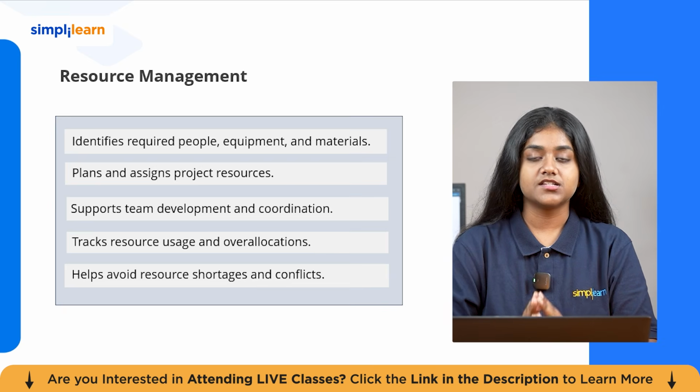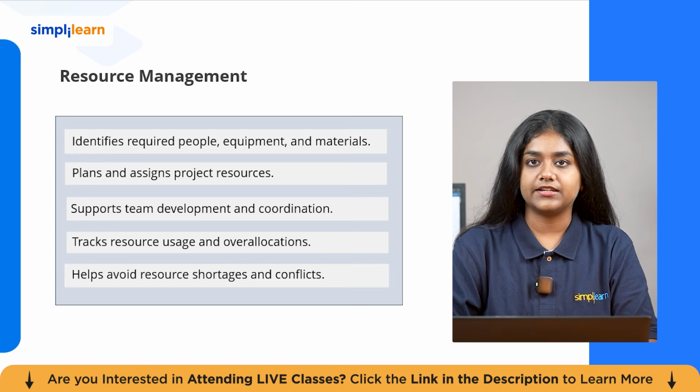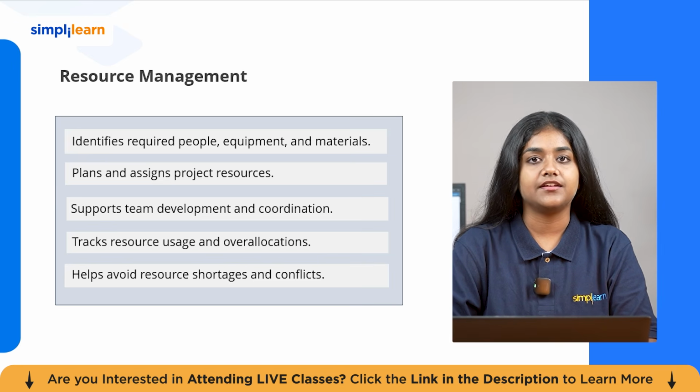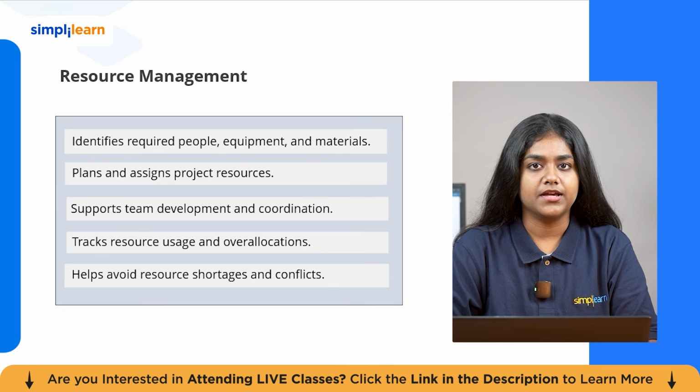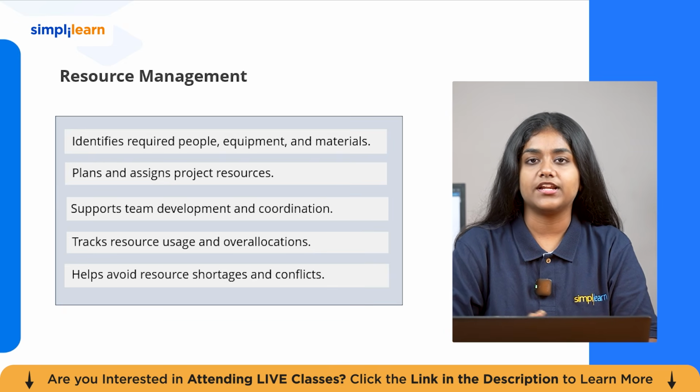In Primavera P6, resource management is fully integrated with the schedule. Labor, non-labor, and material resources are created in the enterprise library, assigned to activities, analyzed through resource histograms, and leveled to resolve resource over-allocation. Effective resource management prevents the two most common problems: running out of key people at critical moments and discovering overcommitment too late to act.